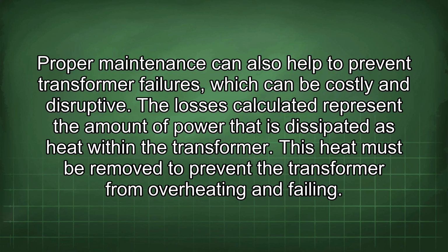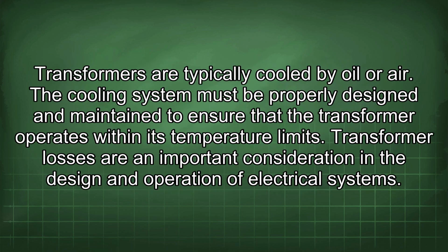The losses calculated represent the amount of power that is dissipated as heat within the transformer. This heat must be removed to prevent the transformer from overheating and failing. Transformers are typically cooled by oil or air. The cooling system must be properly designed and maintained to ensure that the transformer operates within its temperature limits.